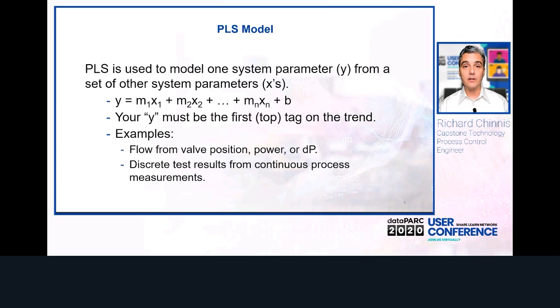And so what we did is we used the periods of time where there was a flow reading and we modeled that flow based on the pump amps. Created a model of that flow so that when the flow itself got so low that the flow meter wouldn't register it, you still had a model of flow based on the pump amps because the pump was still pumping and registering amps.